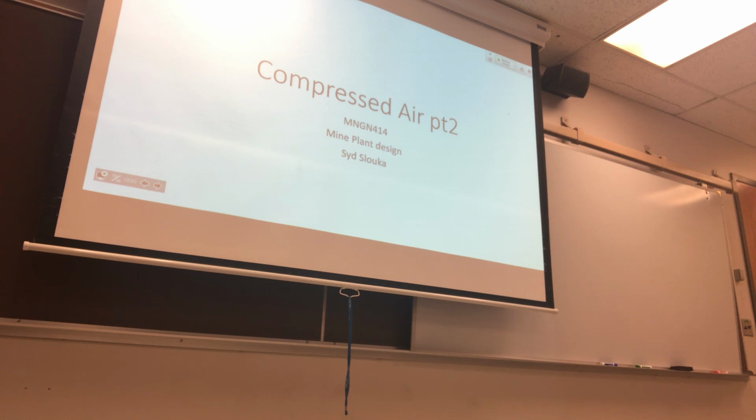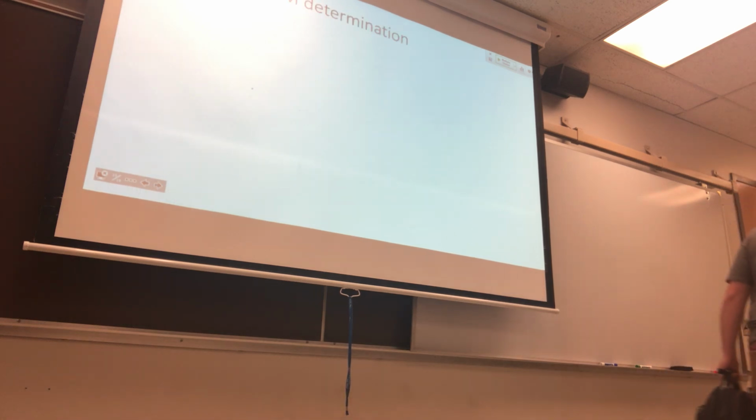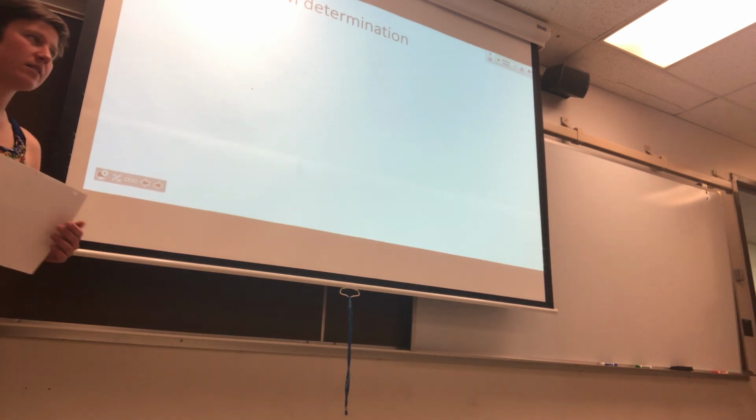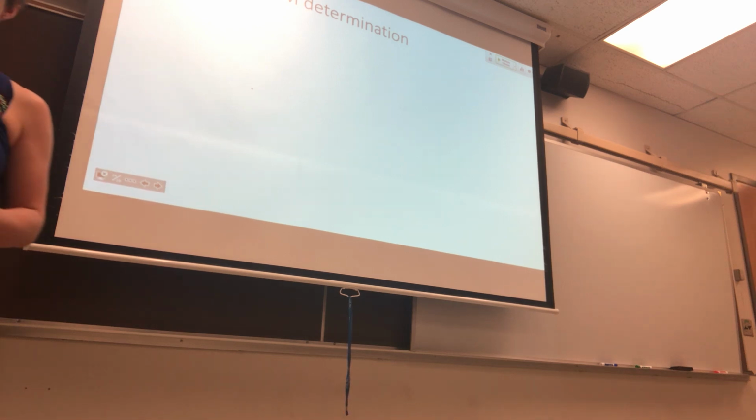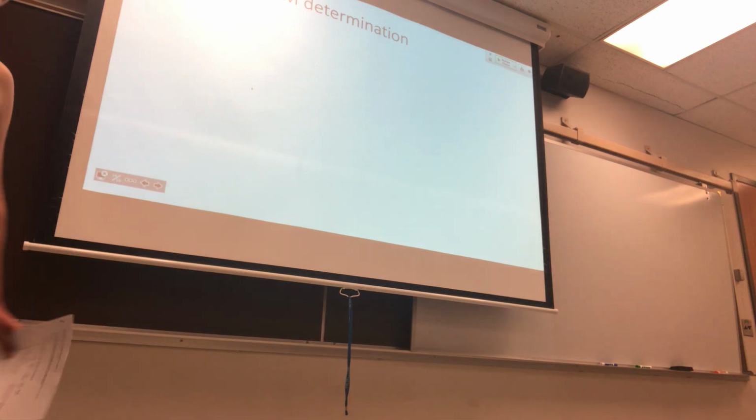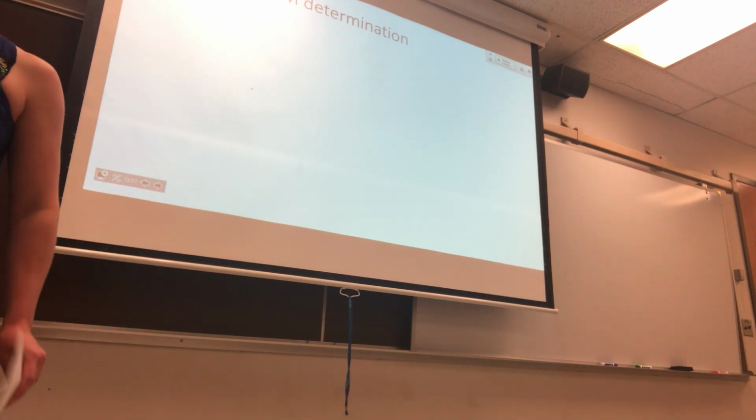So let's continue on with our notes for compressed air. In the YouTube video, they talked about the CFM for a compressor. So we can determine what our cubic feet per minute are for a specific air compressor that we have. Pretty important, so we can see if our air compressors are maybe getting old over time or if there's a leak or something.